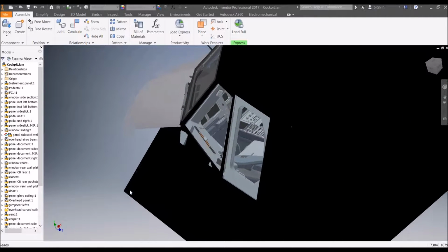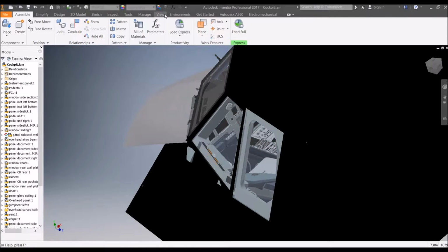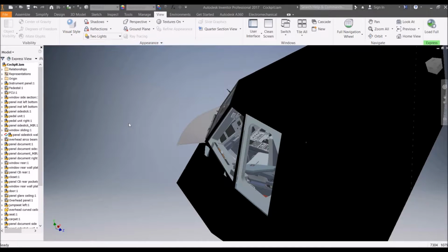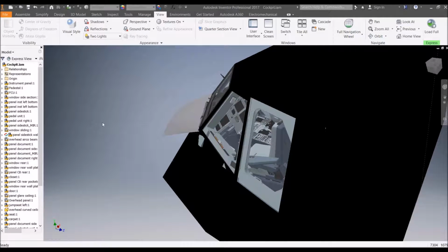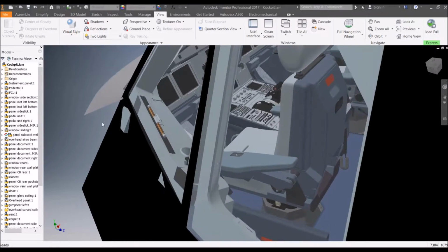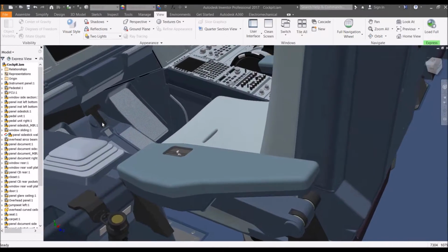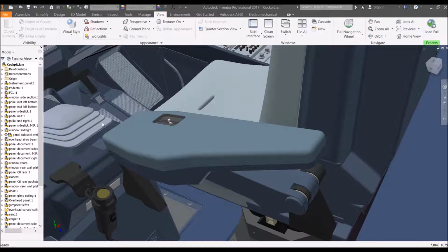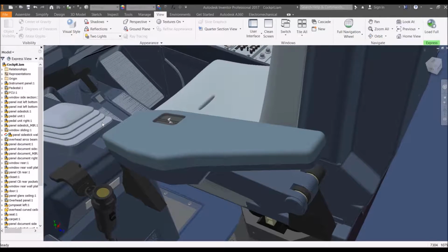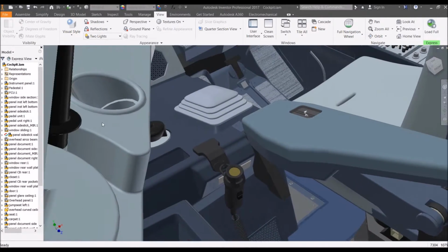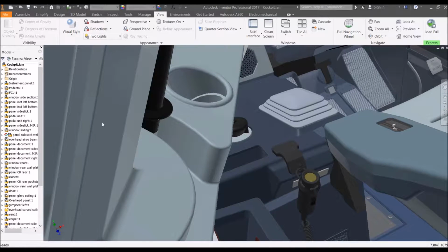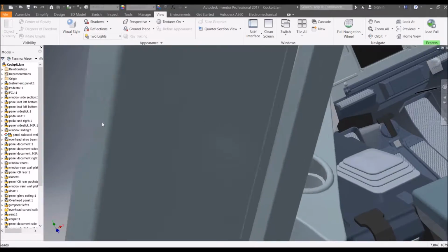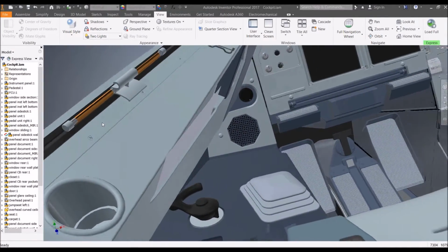There's a few things to keep in mind when you are navigating the viewport using a 3D mouse like I am using. First you want to set the view to perspective, otherwise you cannot move inside of geometry. Second, if you move forward a lot, then at some point the camera will stop moving like this. I'm still moving the mouse, but it stops moving forward. In that case you just release the 3D mouse, move sideways or rotate and then sideways. It's a bit quirky, but eventually you can move inside. There you go.